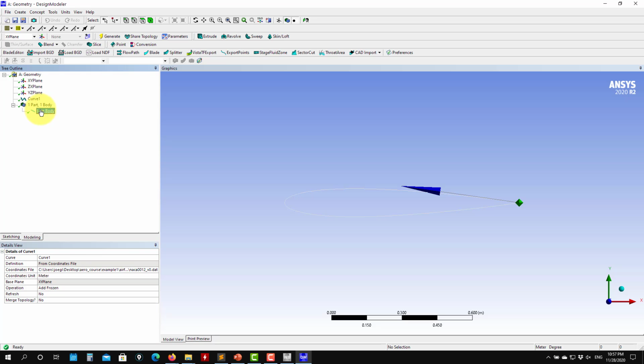What I was telling you is that here you have a single loop. Remember that when we were plotting the airfoil in XFLR5, you can split the data between top and bottom surface, the pressure and suction sides. Here you cannot do it because you have one single surface. So it's a good idea to do the same plotting. But there is no difference in the solution. The difference is how you handle the post-processing data.